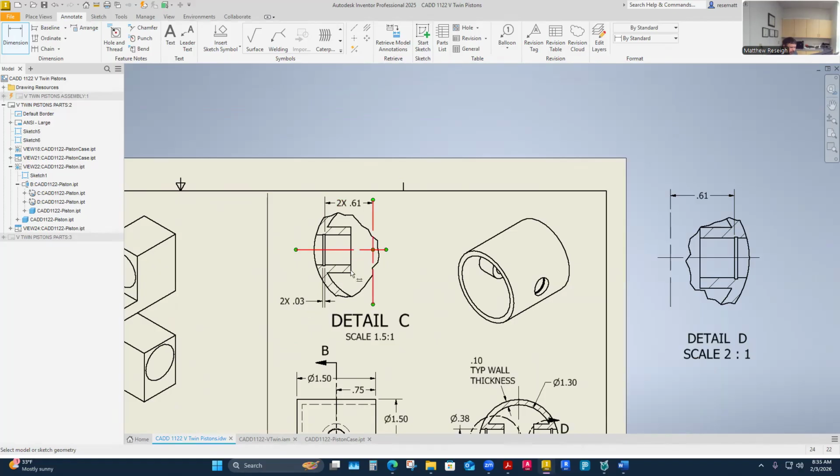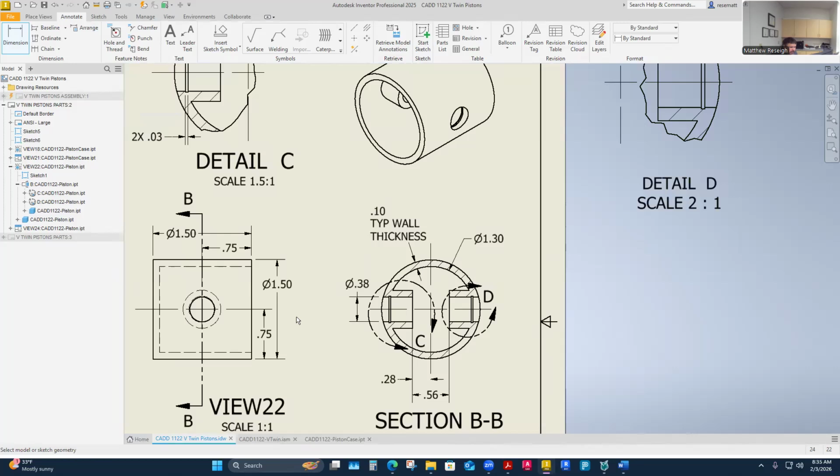Yeah, it might be arguable. Should I dimension it off of here? And yeah, there is some dimensioning that I have done there for that, like 0.75. I've already kind of captured. I view this as more of like the center is controlling this part for sure. This I don't view as really pulling from bottom to center. I really view that, just the overall diameter is 1.5 inches off center. It's 3/4 each side, so it's equally split.